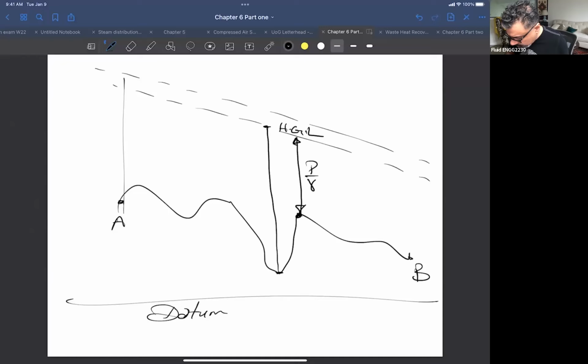Which means that this section of the pipe is going to be made differently from this section of the pipe. We're talking here about kilometers of piping, let's say. So you see the pressure value here is much smaller than this value, which means that the thickness selected for this pipe here will be thicker, or a higher schedule, because now the pressure inside the pipe is higher.